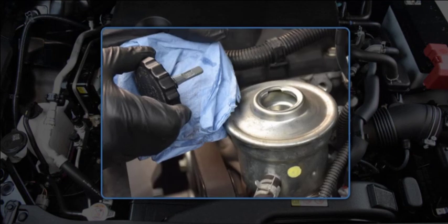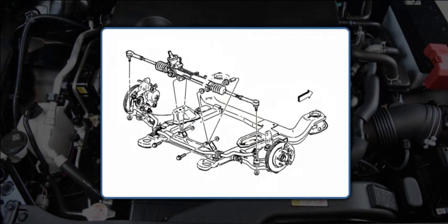Power steering systems can leak at the pump, low or high pressure lines, which are usually not too difficult to replace. Steering racks can also have double seals, which require replacement of the unit, and this may be doable for some vehicles, while others require extensive suspension component removal or lowering the front subframe to remove it. Refer to the service information as you isolate the cause of the leak and what is required to effect the repair.